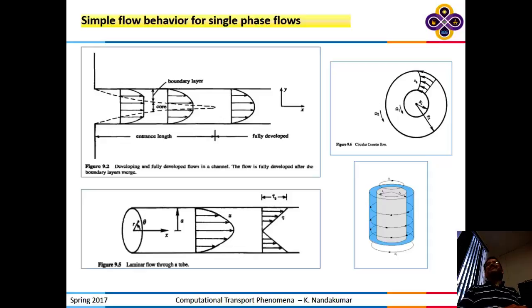Now we have a division of opinion. We can debate it. Why do you say it's honey? So the viscous forces within honey are higher than that in water. So as it's moving through the tube, the development of the boundary layer will be much earlier than what it would happen in water, because there is an inertia. So what you are saying is, if I have very viscous fluid, the boundary layer length would be shorter.